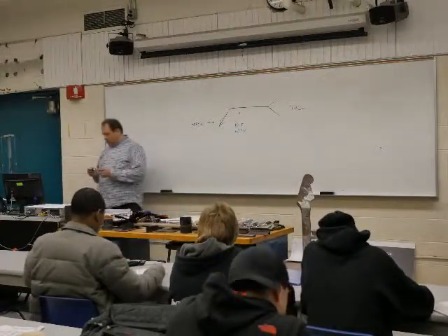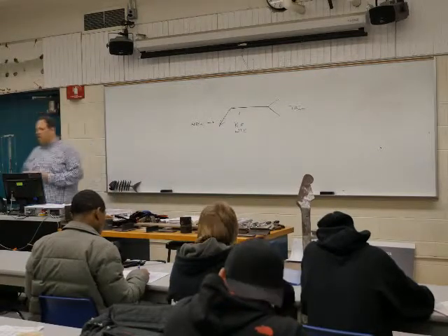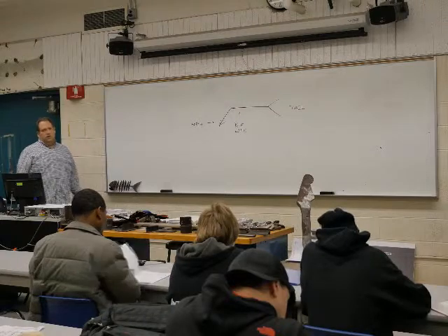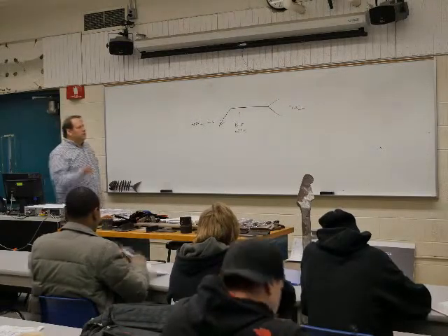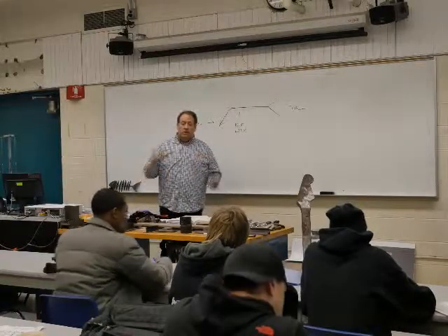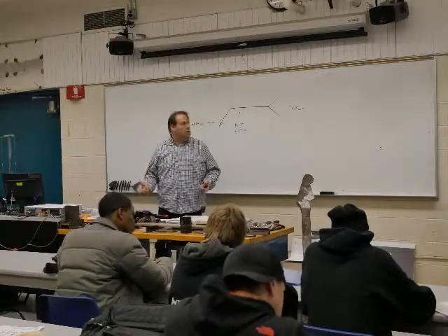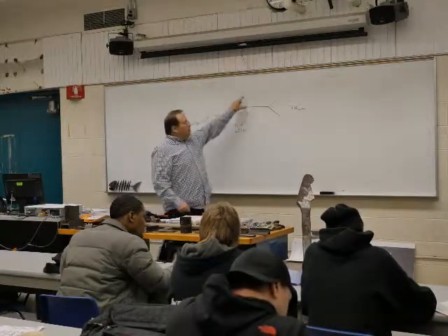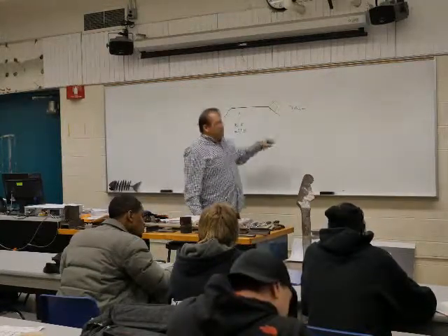Now the arrow is pointing to an area that is to be welded, kind of. I will say it as that because depending on where information is on the reference line actually really determines where the weld is going to go. So the arrow is pointing to something. We're going to come back to the reference line, and then we go to the tail.